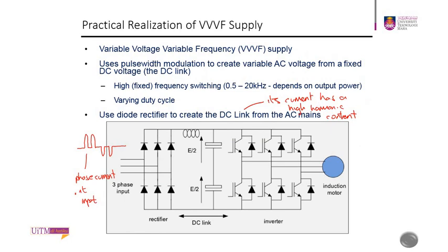Basically it is a rectifier with the inverter before connecting to the motor. For this you can use PWM to create your variable AC voltage. For this system you have a DC link here to connect.